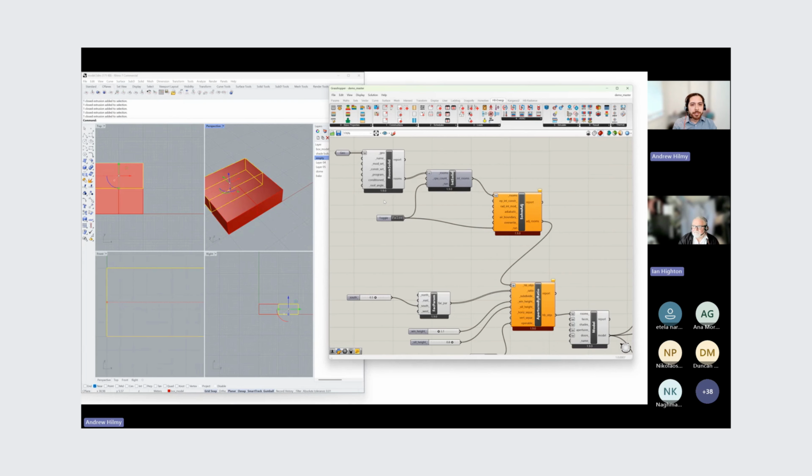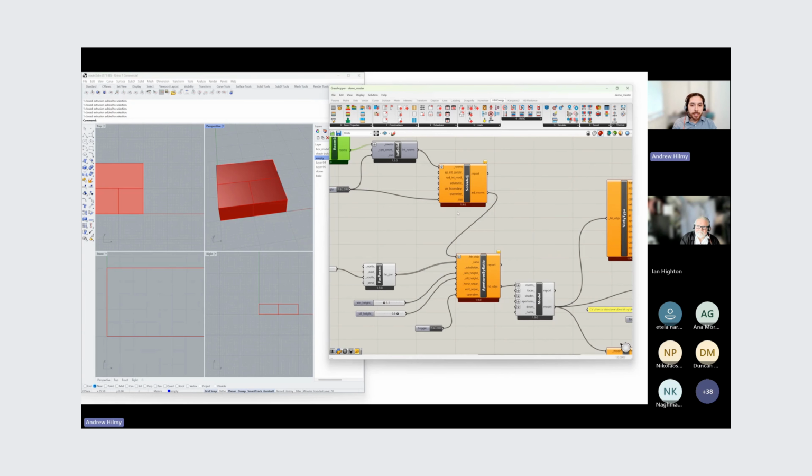So all I've done is I've created a Honeybee room solid here, where I've connected up these geometries. And then I've solved the intersections. The reason I've done that is so that we get matching faces between the zones, and that way we get heat transfer between the zones. They don't come across as adiabatic. And then I solve the adjacency for that, yes.